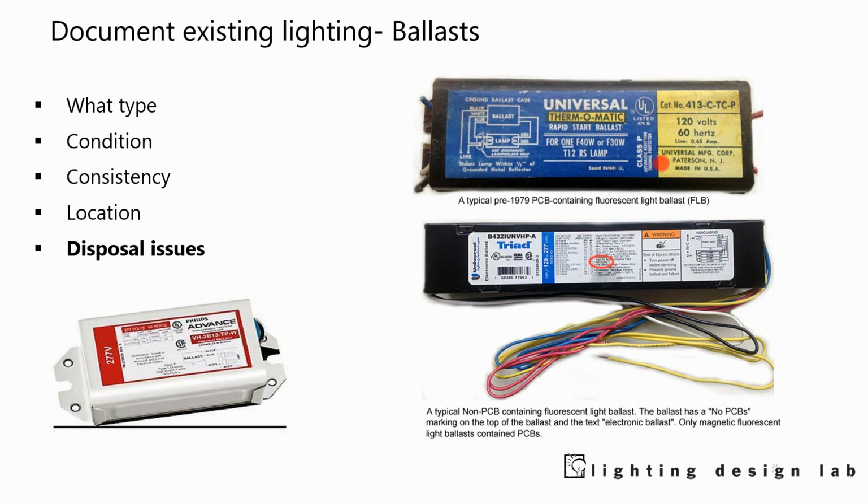And so if you have older ballasts, particularly from before 1997, you have to assume they have PCBs. And in fact, if they don't say specifically no PCBs, you have to assume that they have PCBs. And so they need to be handled as a hazardous waste product, and that can have an impact.